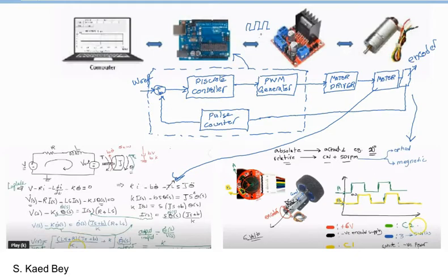So the duty cycle of the square wave as the input for the H bridge is the main control signal for the motor overall voltage. The duty cycle will dictate what voltage the motor receives, and as a result we will be able to control the motor in order to maintain our constant angular speed of 200 rpm.